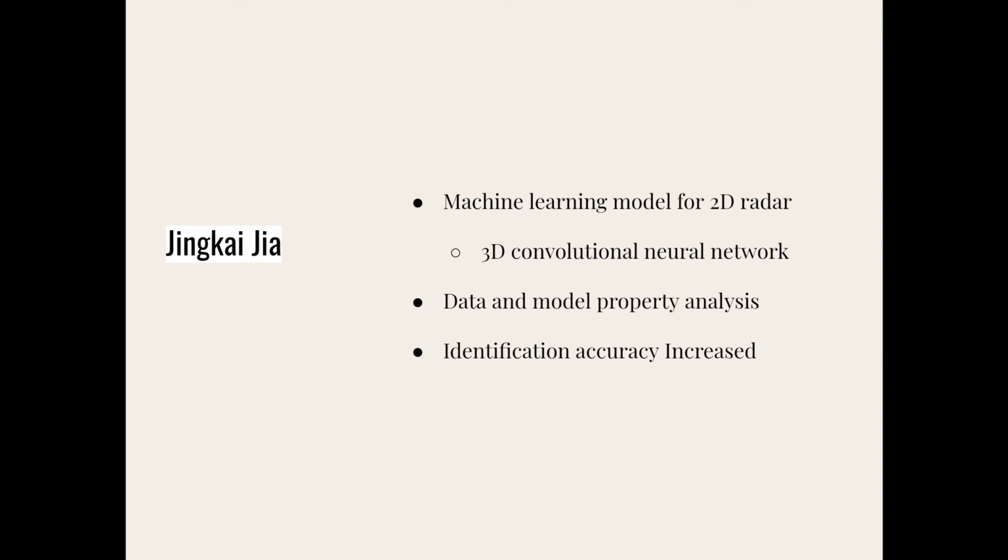After we abandoned 2D radar and switched to 3D radar, I focused on learning the properties of data and model. I performed principal component analysis to learn the separability of the dataset. For example, in the graph, we can see that push and pull can be easily separated. I also performed attention analysis of the model. Attention analysis is a test for what level of noise will make the model change its decision. And from this analysis, I learned that our model is very sensitive to small noises, stretch, and shrink.